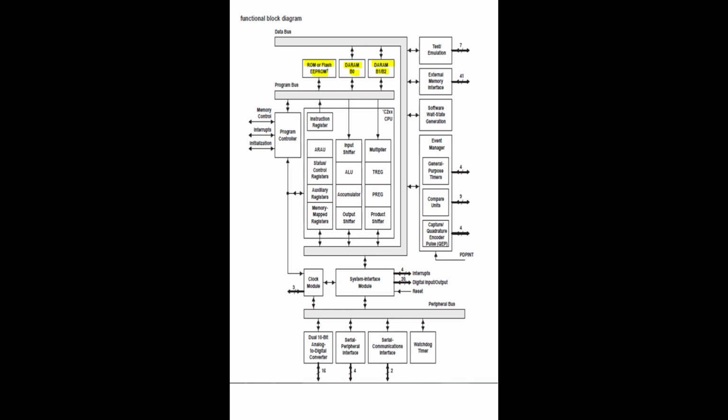And after doing the addition, the answer, 2 plus 5, which is 7, will also be stored in the DRAM B1 or B2 block of memory. So B1 and B2 are only for storing data. That is why it is called data memory. DRAM is dual access RAM. Why is it called dual access RAM? Another RAM is also there called SARAM, single access RAM.